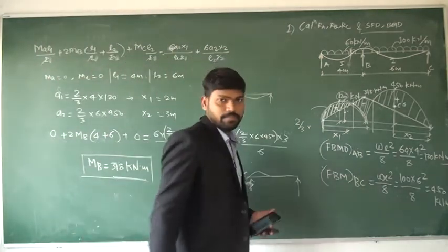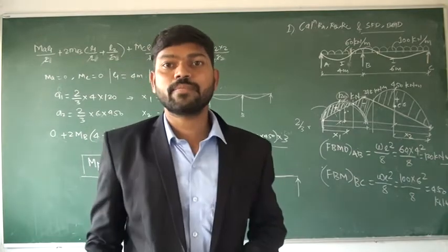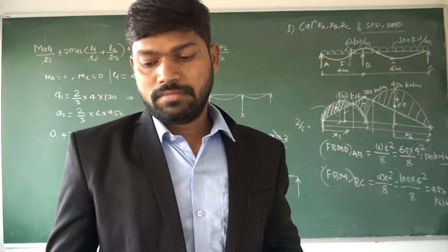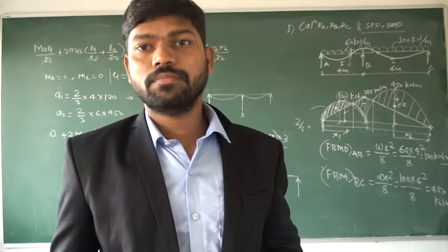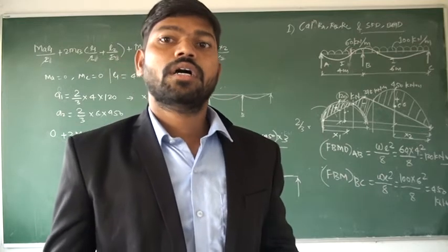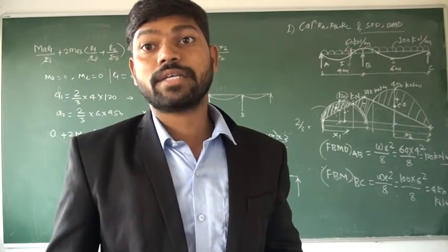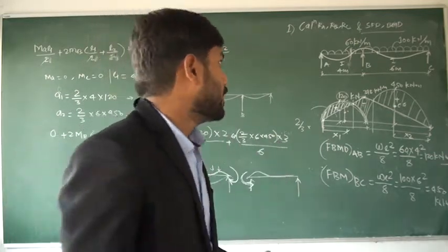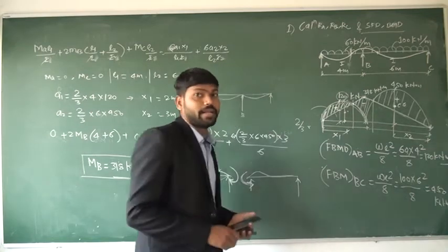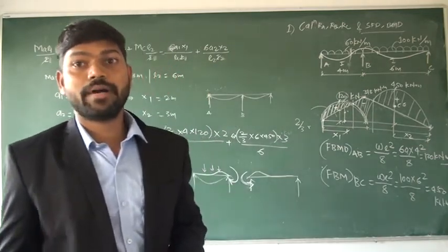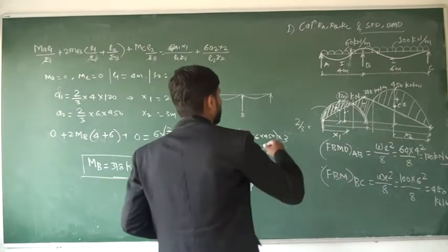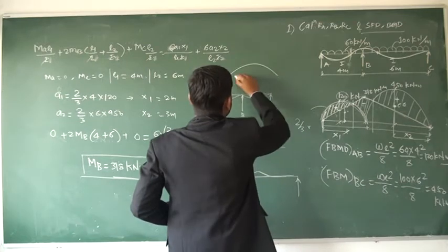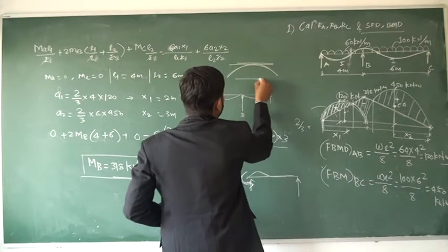See, due to this reason, if you see the reinforcement in the RCC frame structure, at the intermediate support or intermediate column, the beam is provided with extra bars at the top. Now, what is the role of these extra bars at the top? When the beam is going to cause a negative bending moment, like this, definitely tension will be at the top and compression will be at the bottom.